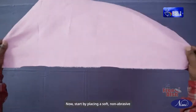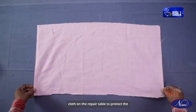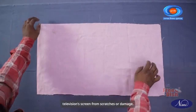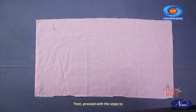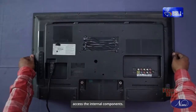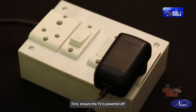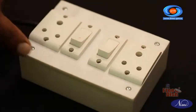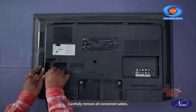Now start by placing a soft, non-abrasive cloth on the repair table to protect the television's screen from scratches or damage. Then proceed with the steps to access the internal components. First, ensure the TV is powered off and disconnected from all power sources. Carefully remove all connected cables.